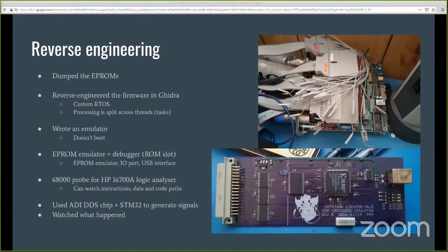So the next thing I did was build this little purple card at the bottom there, which is an EEPROM emulator. There's a 5 volt to 3 volt level translation interface on the left side next to the port that plugs into the EEPROM socket. U4 is an SRAM, a static RAM chip, and the chip on the right hand side there is a Xilinx FPGA, sorry, not an FPGA, CPLD. That's the XC95144, 144 macro cells and a lot of I/O pins, and frankly the I/O pins are what matters here. On the far right of the board you have an FTDI FT245, which talks to the Xilinx chip, and then a USB port and a couple of LEDs. JTAG port on the bottom, of course.